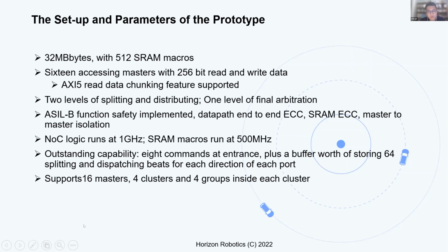As shown in the previous slides, two levels of splitting and distributing NOC logic are implemented, and one final level of arbitration is implemented before the SRAM banks to merge all the traffic from masters to every single SRAM macro.